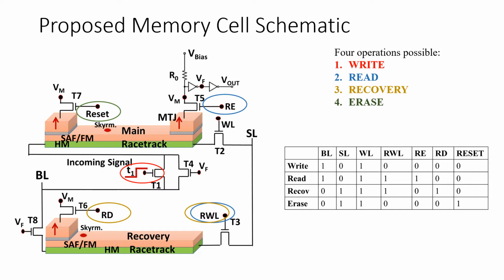When the skyrmion reaches the MTJ underneath the racetrack, the MTJ's resistance changes, because that's how an MTJ works. It sees a different resistance depending upon the orientation of the magnet underneath, or the orientation of the racetrack underneath. So it reads it, and there's a read enable, so you can actually read it, and you see a V out, voltage out, and this basically turns off this transistor. So that you stop every operation, and whenever that blip happens is when you have recovered the time.